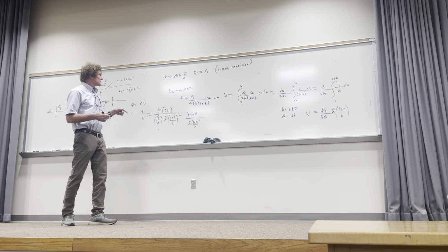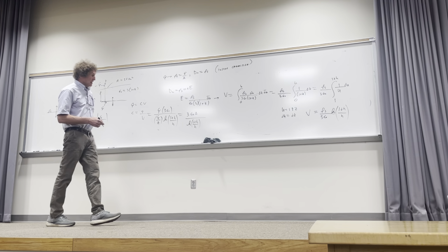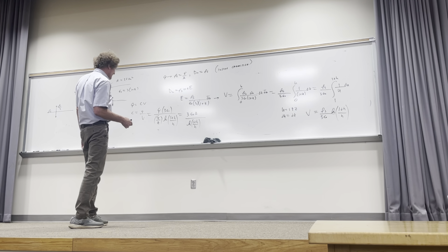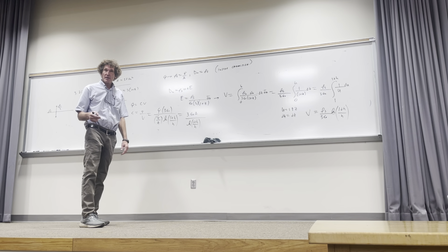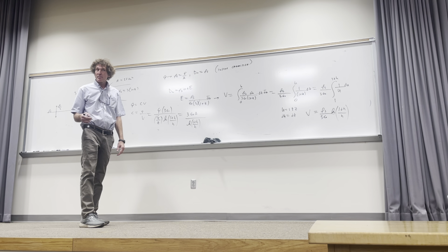When you plug in the values, you got to make sure you get the units right. That's 50 centimeters squared. So if the units of capacitance are going to be in farads, you're going to have to change this to be equal to 50 times 10 to the minus 4th meters squared. Y'all follow me on this? Because that's centimeters. Centimeters is 10 to the minus 2 meters. If you square it, you get 10 to the minus 4. And you'd also have to make sure H is 1 centimeter, which is 10 to the minus 2 meters, and you would do that problem that way. Agreed, class? Does that give you the right answer? It does.